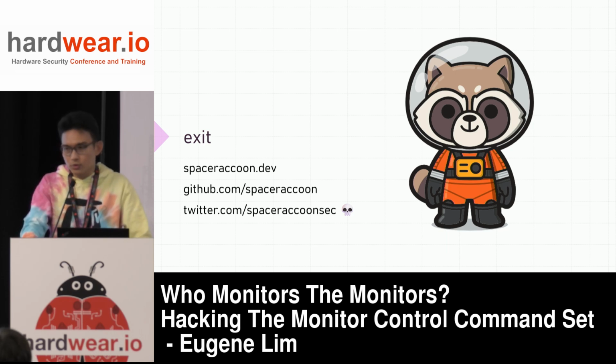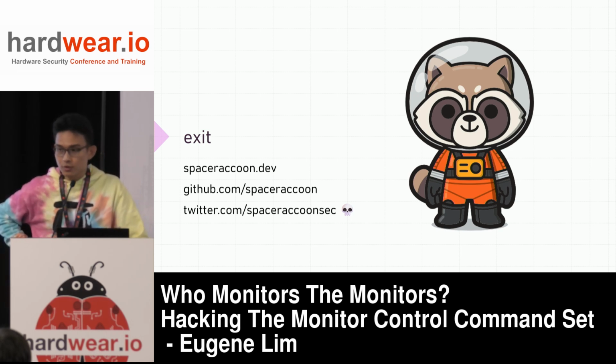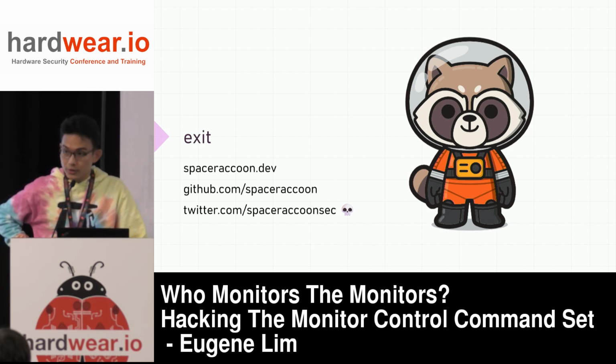It's definitely doable. So as mentioned, Max Thomas has done a live flashing of the firmware running on the monitor itself. There's not a lot of protections, maybe some encryption of the firmware when you flash it, but overall it's hard to figure out because, as mentioned, it's very specific chipsets, like the Genesis chipset, and very specific instruction sets that don't work well in your typical reverse engineering software. So I've looked at it, but haven't made much progress there.